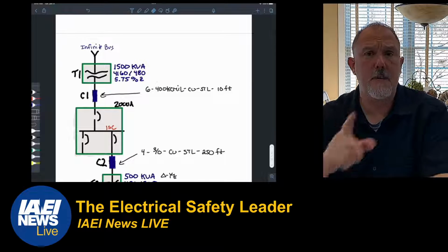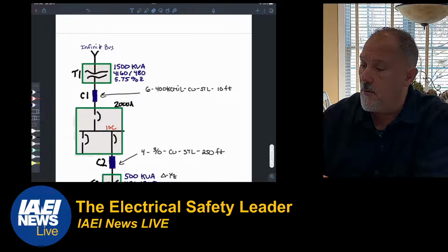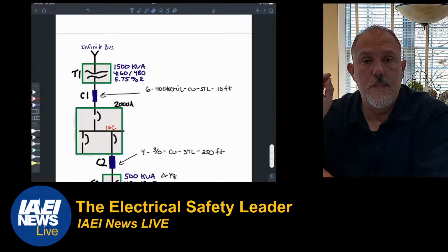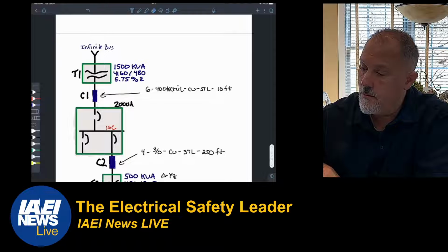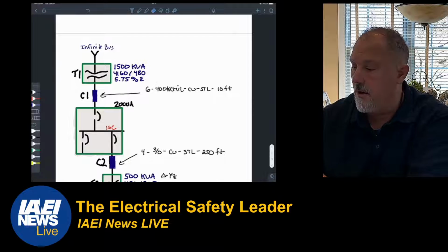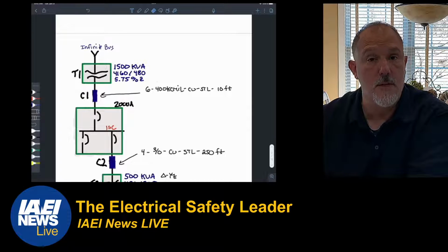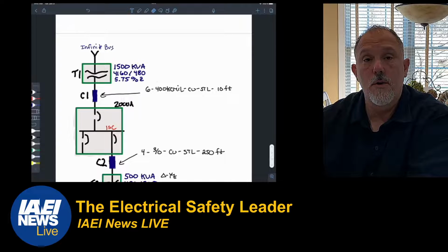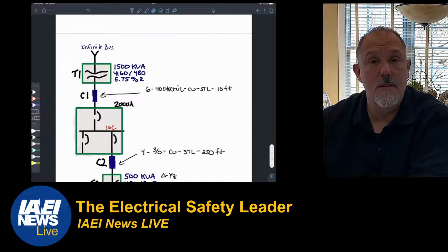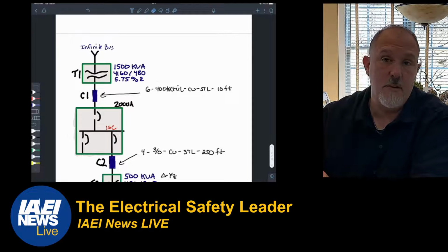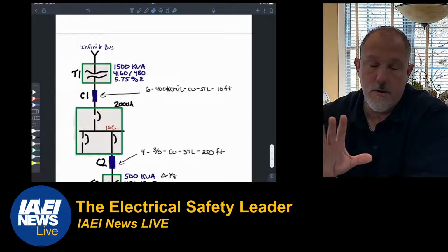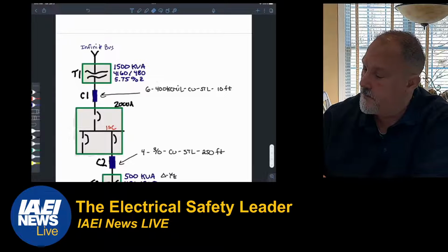We're going to start with an infinite bus, but if we've got time, we'll assume an available fault current on the primary of this transformer from the utility, and we'll convert that to a per unit impedance, and then we will see what it does to our fault current calculations. Because once we have the per unit values calculated, we're happy boys and girls.